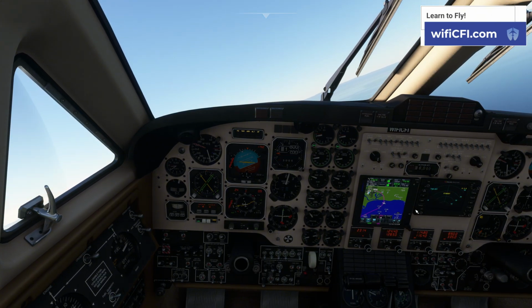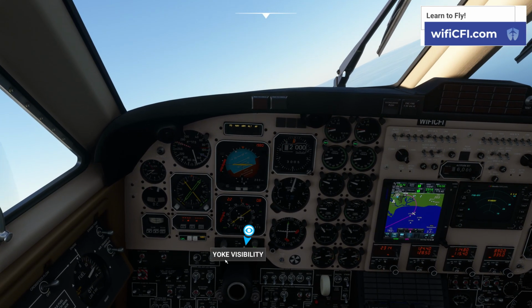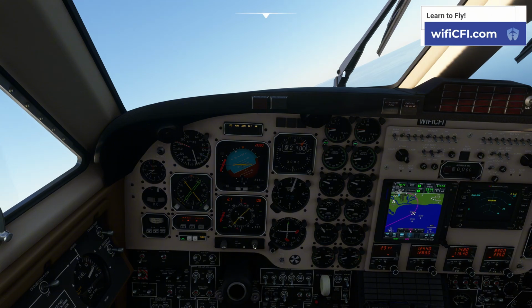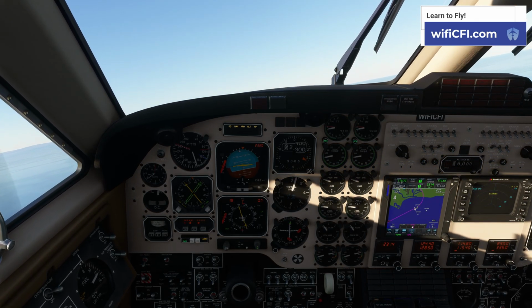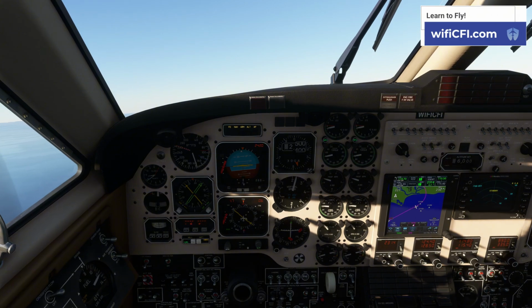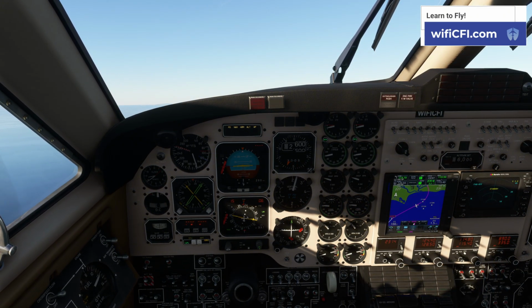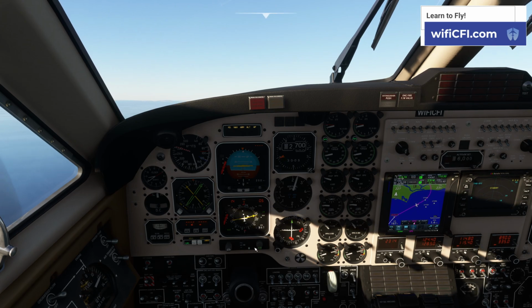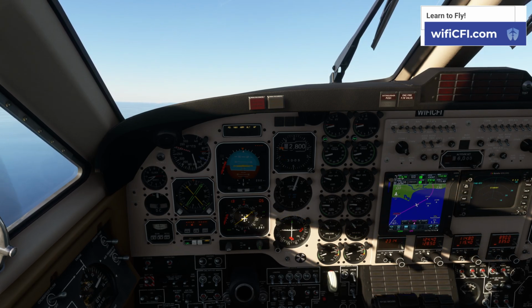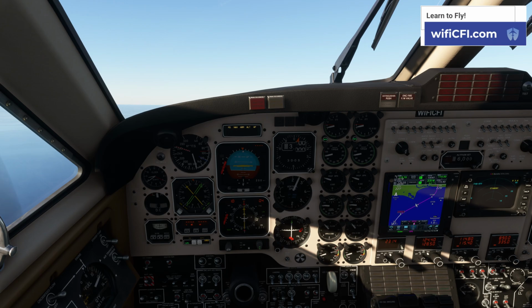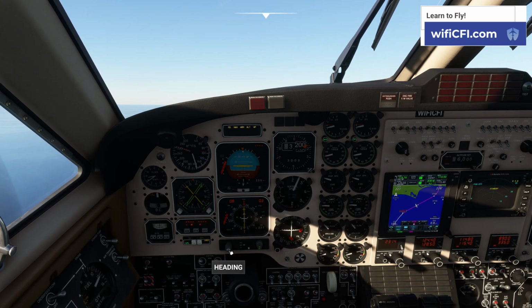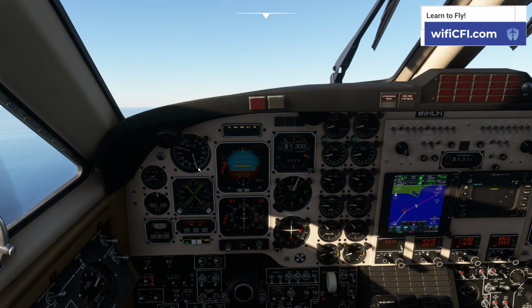And we're off on our departure procedure heading up to 6,000 feet. New desired track is 227. Look at this. Let's go ahead and put this on. Going the long way around the horn. Sync up our heading bug. Altitude's looking good. Airspeed is looking good. We're climbing just fine. Awesome.